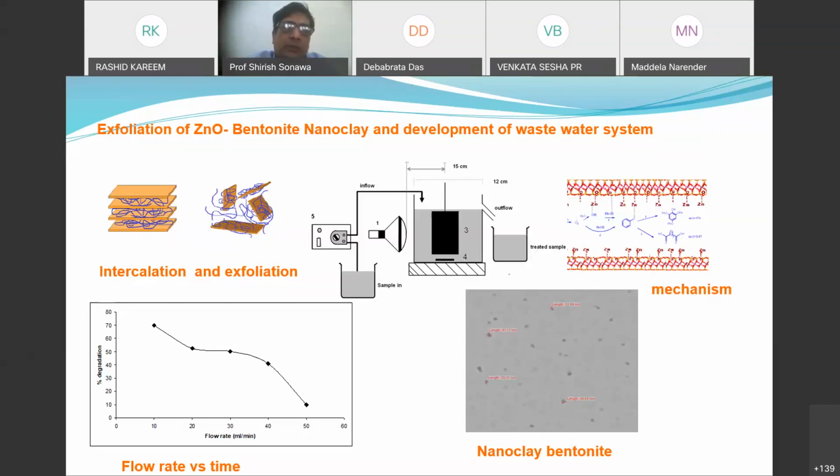Earlier, they were using talc as a filler, but the problem was that because of the addition of talc, let's say if you want to make a dashboard or a bumper, almost 40% of filler we have to use. And because of that, the properties were not improving much, but the weight was going to increase.